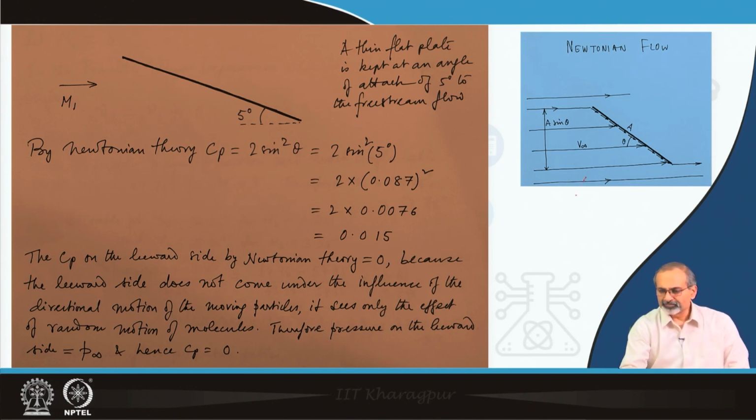We would like to revisit the Newtonian flow model, which we said works very well for hypersonic or hypervelocity situations. And we would like to compare the case with a slightly lower Mach number range, where we usually use shock expansion theory applications, and then try to compare the result of the shock expansion theory with that of the Newtonian flow and get a comparative picture.